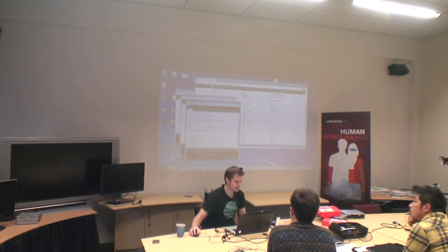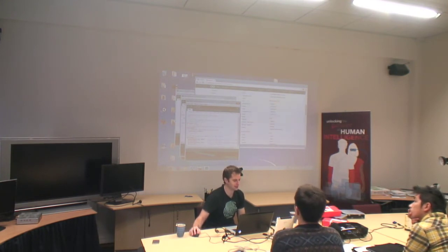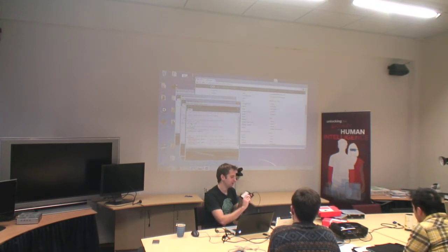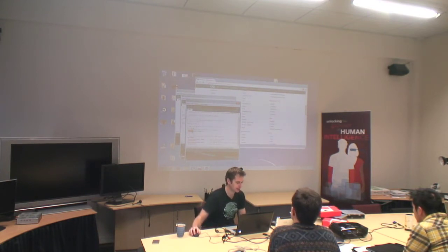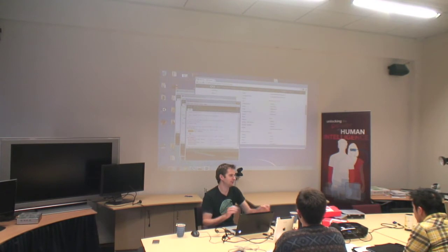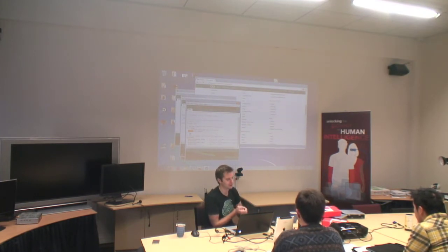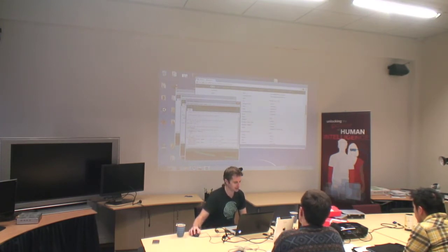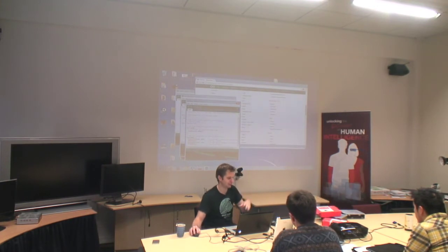So let's have a look at this code. We create an integer called LED, and we'll define it as 13. So that's basically going to be the pin we're working on, pin 13, which also happens to be connected to that little LED. So we have this pinMode function. PinMode basically defines what sort of mode we're going to use the pin for. Is it going to be output, so we're going to be outputting 0 volts to 5 volts on it, or is it going to be input, so we're going to read either 0 volts or 5 volts from it. So we say pinMode LED, which is equivalent to pinMode 13 is output, so we're saying, okay, set up pin 13 to be an output so I can put voltage on it.